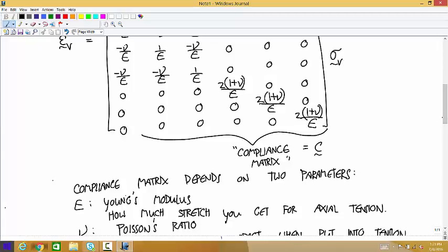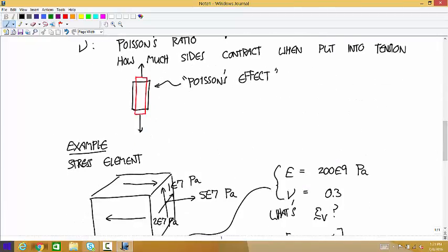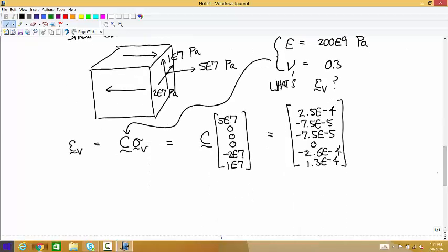So can you also say then that the x direction is in tension, and the y and z directions are in compression? Can you think of it that way too? I would use the stress to think about it that way, and I would use the strain to think about how the shape changes. So from the stress tensor that I gave, you can look at this and see that we know the x direction's in tension because there's a force that way. The negative face that's obscured is equal and opposite, so it's pulling that way. And that's how you know what the loads are doing.